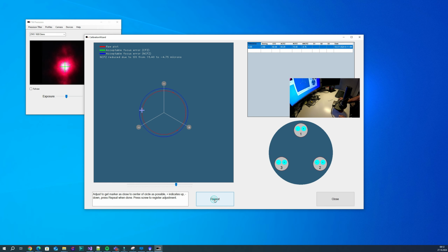As the wizard text indicates, it is now time for adjustment. Don't forget to rotate the instrument to the starting position. Pressing Continue gives a real-time view. The plus-minus signs on the drawing indicate the direction to turn the screws. Plus is raise, while minus is lower. Select screws and turn until the plot marker is centered. When done, press the button and start a new measurement.